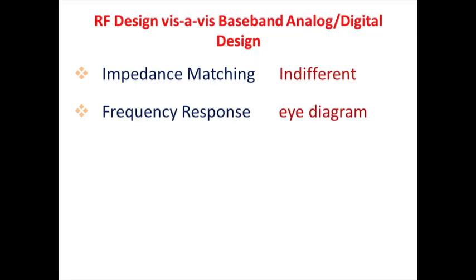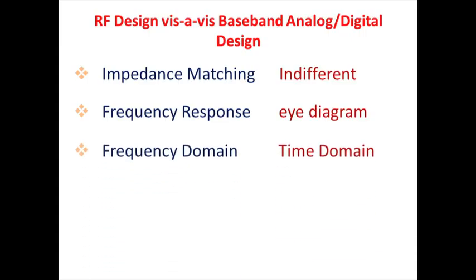Like a capacitor, at a certain frequency it can behave as a capacitor, but if you change the frequency it may also become a resistor or an inductor. The same thing for an inductor becoming a capacitor at some other frequency. So, frequency response is an important thing, and you should always be aware that if you change the frequency, a whole new circuit from the same components you can get. So, that is why frequency response is a very useful thing for RF design.